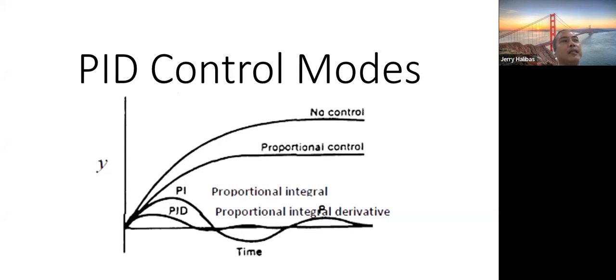So one way or another, sometimes there will be a mismatch. Sometimes the available final control element, let us say the control valve or the proportional control valve, has a bigger size in terms of the pipe diameter as compared to the existing piping.